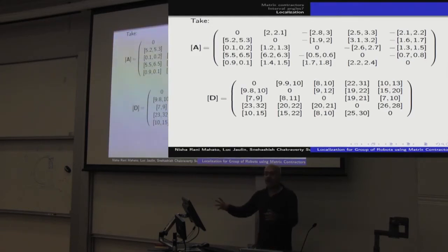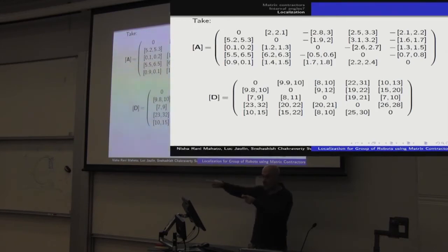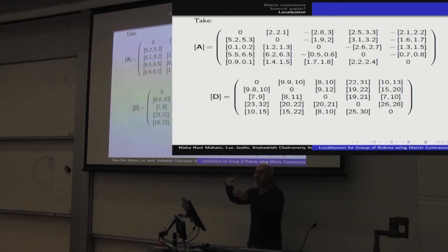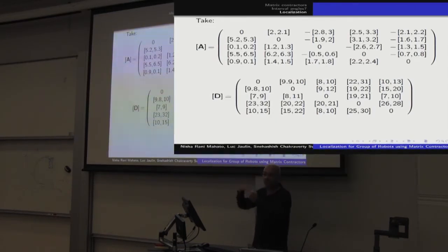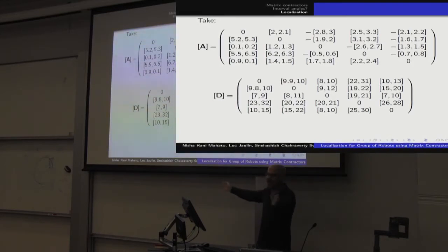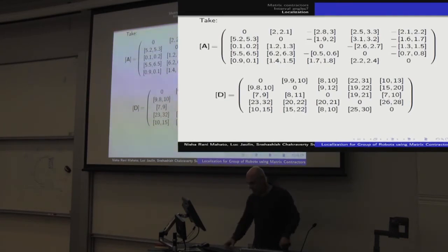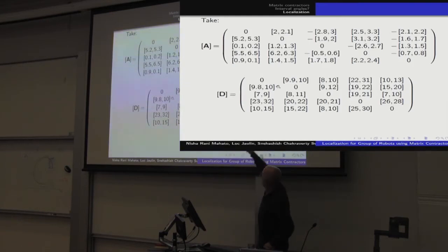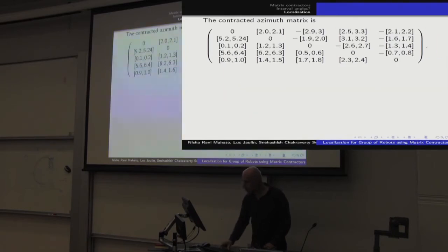But even in our application, even if the robots are far, when they are just near to you, you can see with a good accuracy thanks to the cameras. But when they are far, you have some information about where they are due to the sound, and you know where the sound comes from. But it's a bad approximation. But it's less than pi approximation. It's not too large. So the distance matrix most of the time is due to ultrasound. With the sound, you can get the distance between 2 robots.